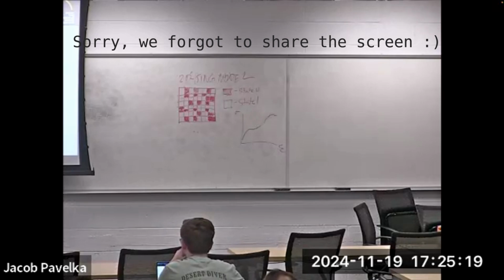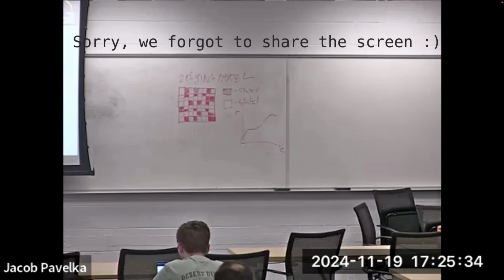So there are two approaches to these types of problems generally, continuum plasticity or crystal plasticity. Continuum plasticity is the kind of thing you probably would encounter if you have used Abaqus to do some plasticity problem. We are zooming out to the large scale of the material and not considering any details about microstructure, about grains, about these kinds of things.